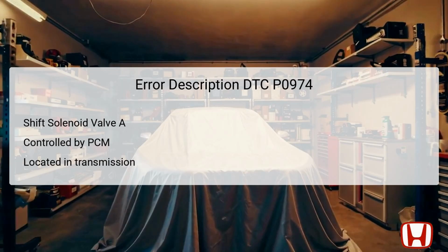DTC P0974 refers to a malfunction of the shift solenoid valve A, which plays a critical role in controlling the hydraulic pressure that enables gear shifting in automatic transmissions. This solenoid valve is operated electronically by the powertrain control module, PCM, integrating various inputs to facilitate optimal transmission performance.